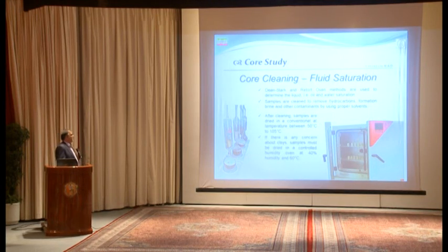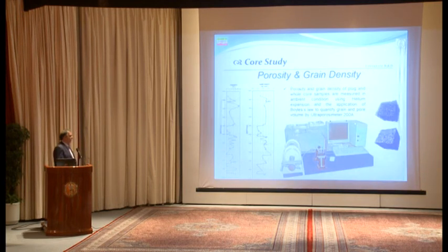And also cleaning and fluid saturation measurement. For fluid saturation measurement, we have two methods, Dean-Stark and retort method. I think that you are familiar with these methods. And for drying, we have to clean the sample and dry it under humidity. Porosity measurement uses standard equipment for measuring porosity.